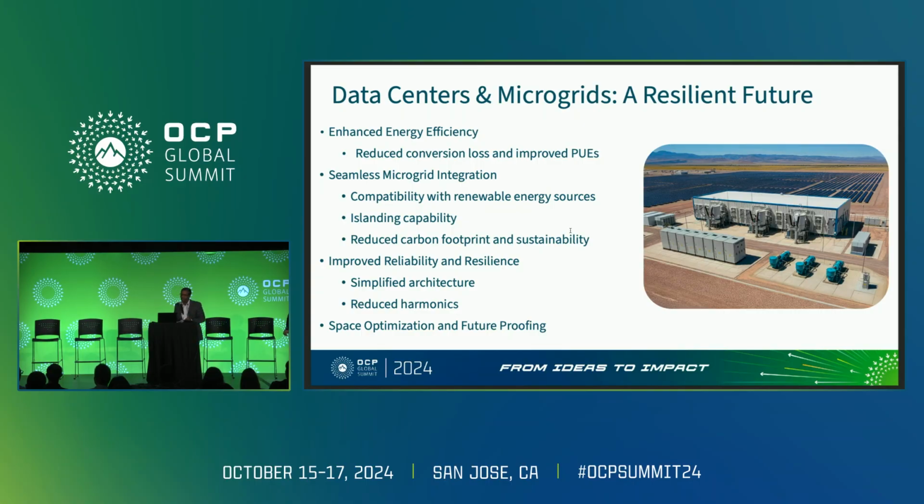that are cleaner sources. How does that tie into DC? Well, if you look at most of our distributed energy resources today, they natively produce power at DC. Most of them use something called IBR, or inverter-based resources. So if you're talking about eliminating the inverter to improve the efficiency, then you can directly tie sources like PV, wind, and battery energy storage systems onto your DC bus, providing a more stable power input into your racks, along with shielding your system from grid disturbances. So this is a pretty exciting field personally, and there's going to be a lot happening on this side, especially as data centers become more and more power hungry and we start to move towards on-site generation.